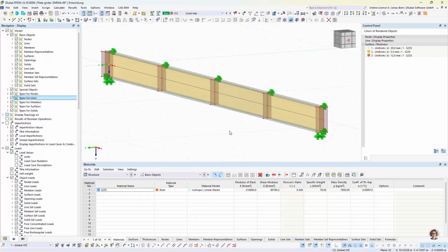Okay, so now the last question is, how do we combine all these imperfections together? In Eurocode 3 part 1-5, we have a combination rule for equivalent geometric imperfections. We have one primary imperfection that we assign with 100%, and the other ones we take with 80%. But just to make things a bit simpler here, I would just take them all with 100% amplitude, because in most of the cases, there are always 1 or 2 imperfections that are not really relevant or critical for the end result.